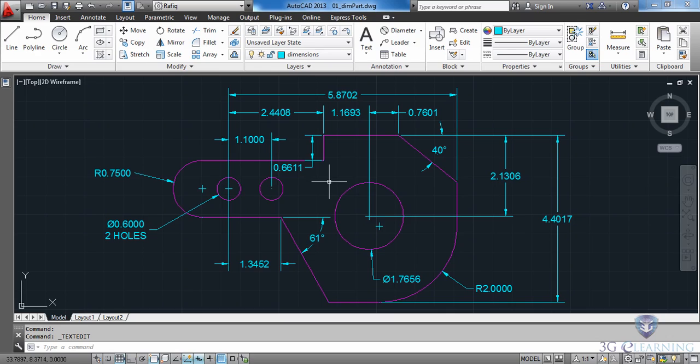The best way to know if you have enough dimensions is to pan the drawing over and try and recreate the geometry from your measurements. If you're missing one, that's how you're going to find it. With a little practice using these tools, you can quickly transition your design from an idea into a constructed project.